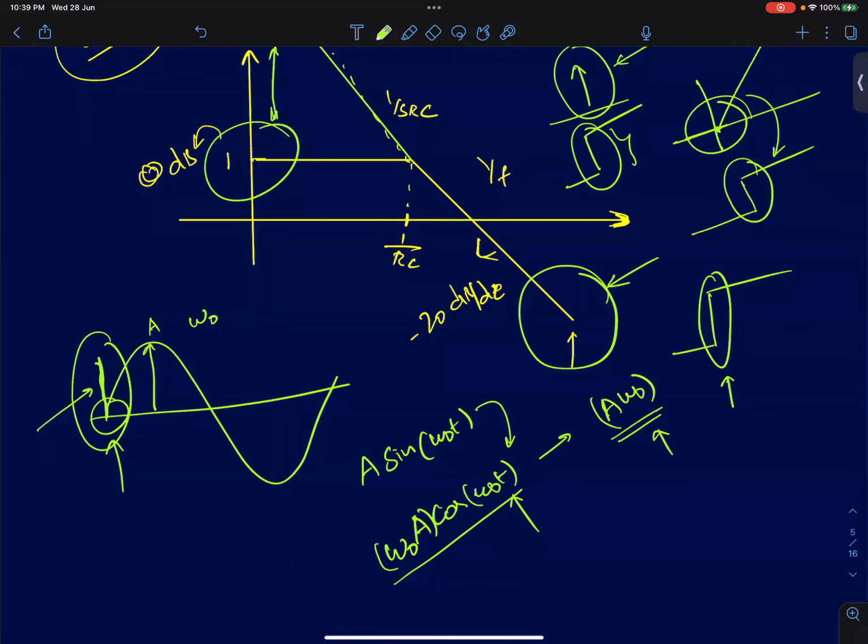And you guys already know what frequency response is. It contains everything you need to know about how the system behaves for different frequencies. So if you're applying a sudden change, you should look at the high frequency range of your frequency response and try to predict its behavior.